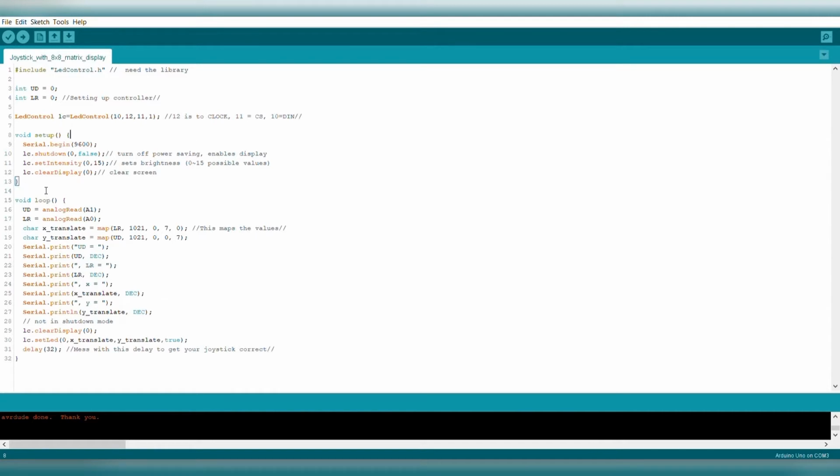Now there are 2 really essential functions in any Arduino program, and those are void setup and void loop. The void setup is used for you to initialize variables, objects, or the entire Arduino before it executes the void loop. The void loop is a function which executes endlessly unless you have cut the power supply to your Arduino, and this is what we are gonna be working with.